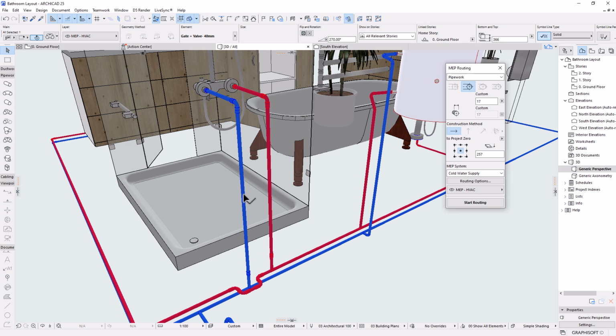So what I need to do is to select this and add a stop valve for both the systems, because we want a situation whereby if there is a leakage, we can just close off the shower and then not affect the entire system for other parts of the bathroom. So what I need to do is to select this line or this pipe, and then I'll hit delete.